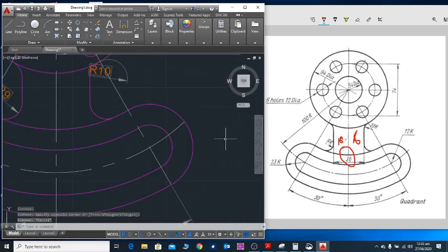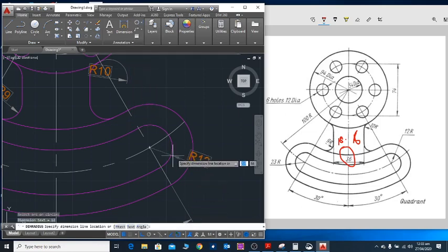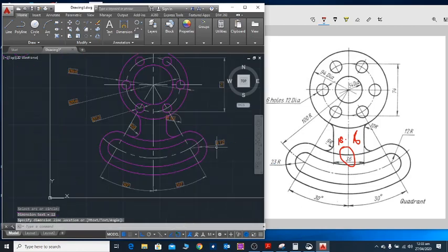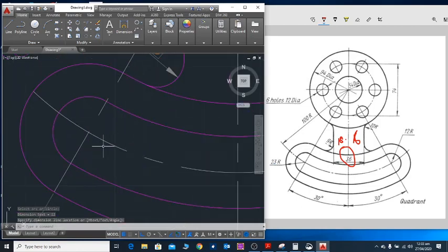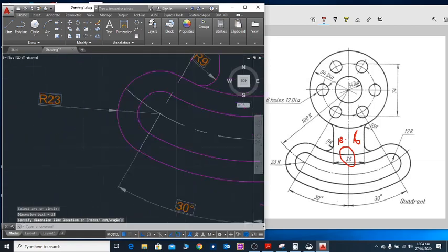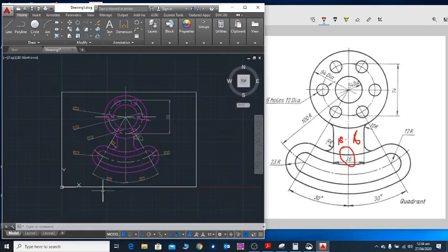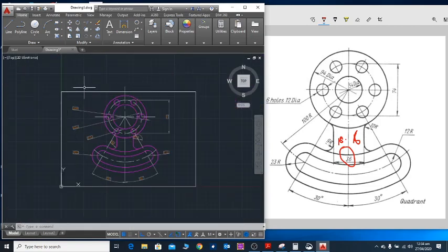I will measure that. I will now measure here. We'll use radius. Select radius and make this point, that is 12. Radius 12. You press the enter key, or you right click. You select this point and this point. So I've done all the dimensioning. If you check, the drawing enters exactly into our paper, the paper we're going to use to print it, which is A4 paper.